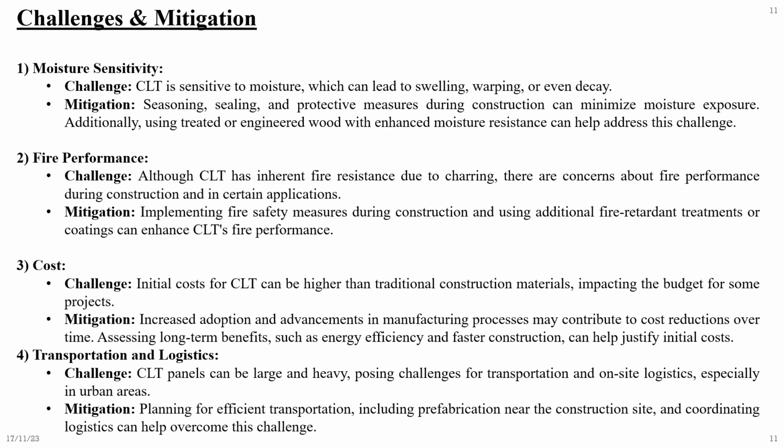Transportation and logistics challenge. CLT panels can be large and heavy, posing challenges for transportation and on-site logistics, especially in urban areas. Mitigation. Planning for efficient transportation, including prefabrication near the construction site and coordinating logistics, can help overcome this challenge.